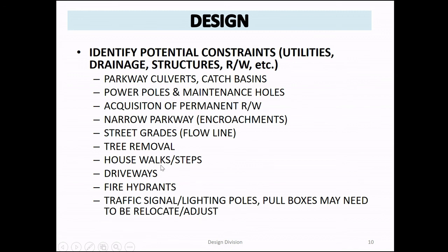If you're depressing the curb ramp, and it's in all parts of the county, there are driveways that are really close to the curb return. So if you're depressing the curb ramp, you have to reconstruct the driveway and depress the driveway, unless you can get a 7.5% transition from the curb ramp to the driveway, but it's hard. This could be a conflict, and this is what we were just talking about before.